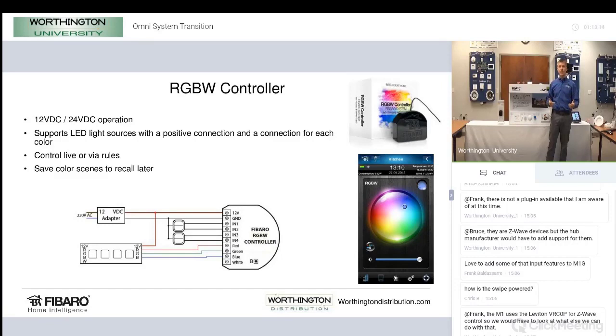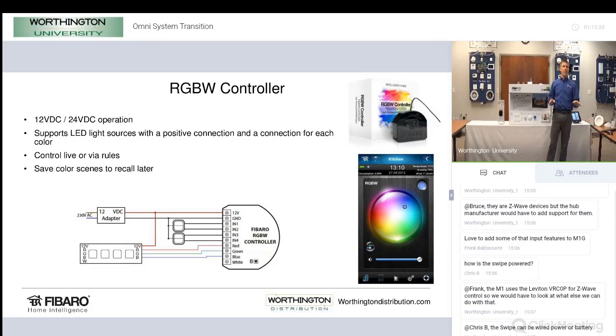So one thing we love to do is say something like, if there's water detected in any of the flood sensors in the house, rather than maybe having alarms go off and beeping and having it be really intense, we can say take all the RGBW color changing lights and have them alternate between maybe blue and red. So blue and white. So go back and forth, kind of indicate water. You'd also get a push notification, but it's a softer approach to notifications.